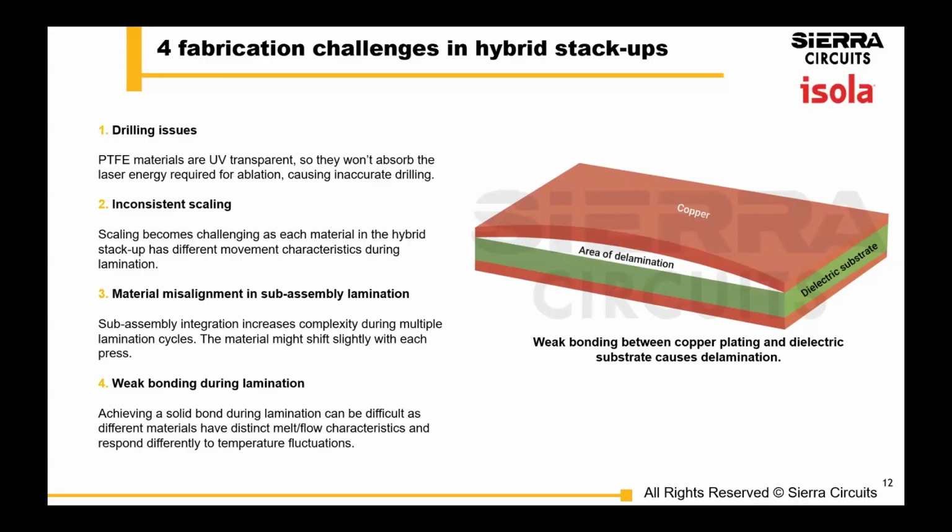Second, every time you have your drilled vias in different via structures, which result in sublams, those sublams also might shift differently. So it's important, again, to understand how the different sublams might shift to get that scaling data. And other than that, if you pick a PTFE material, there are definitely some considerations for that.